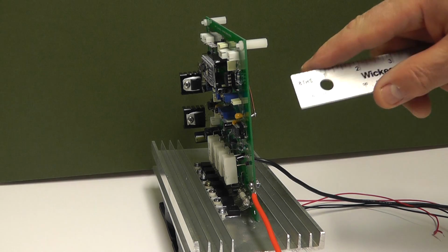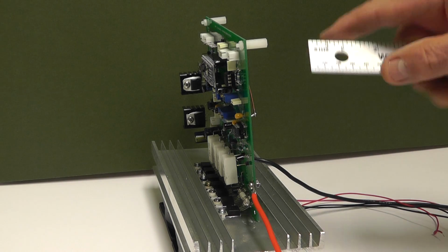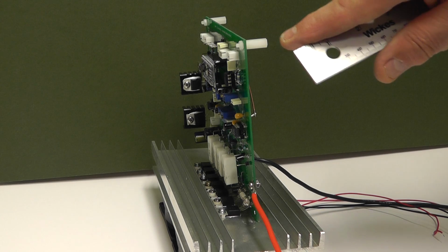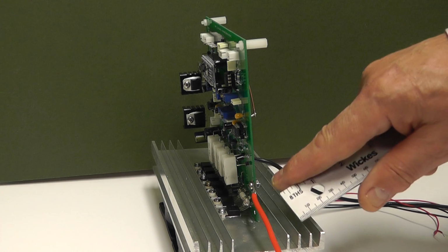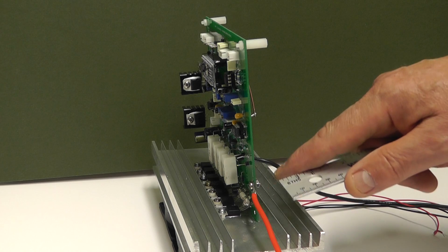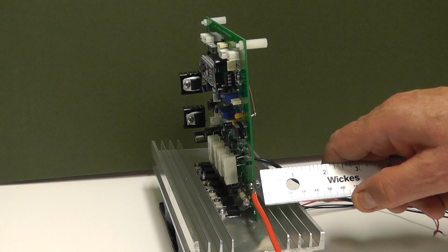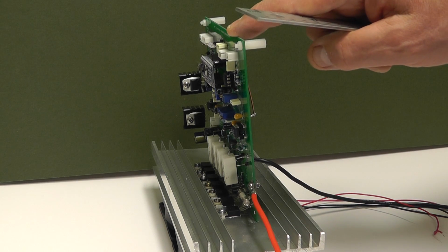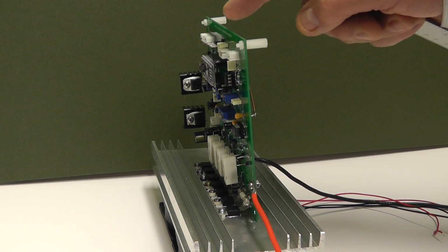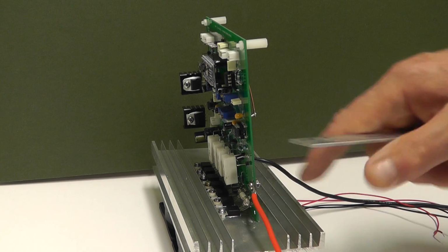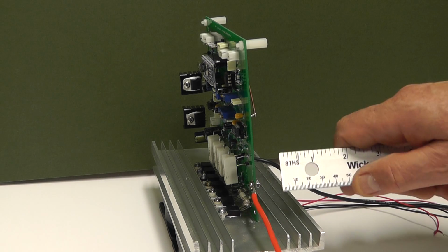Now before we mount the printed circuit board and the heatsink into the project case, we just need to raise the front of the PCB to the same height as the rear, where it's clamped effectively to the heatsink there, by the power transistors. The actual board itself is not bolted to anything at the back. It's really just supported by the legs from the power devices bolted on the heatsink.